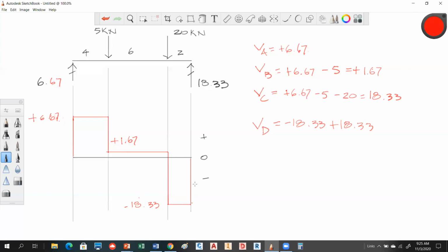Yeah, but that VC and to the right where you did the calculation, should that be negative 18.33? It should be. Okay. Yeah, sorry about that. And would it be VA then? VA, because that's the highest one. Well, no. Remember, we don't look at the sign, okay? You look at the absolute value. Okay. So this is the point of maximum shear. Actually, it's the value of maximum shear. So you would call it shear max, and it's 18.33. That's it. Okay. Does that make sense?